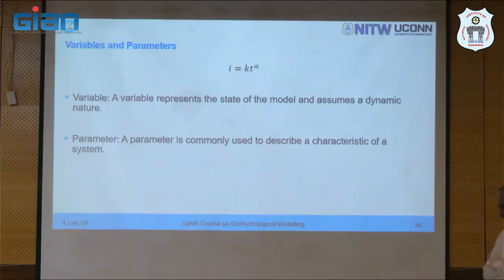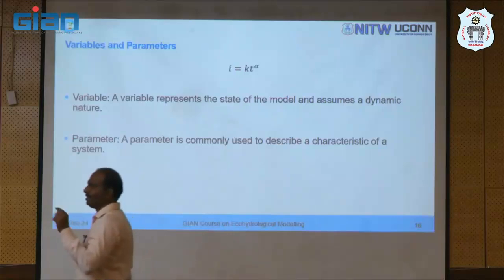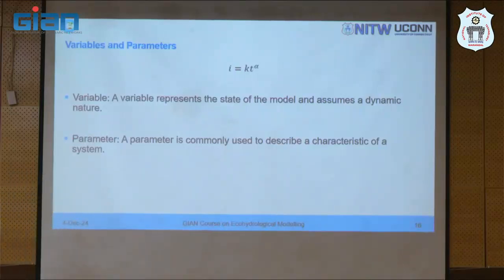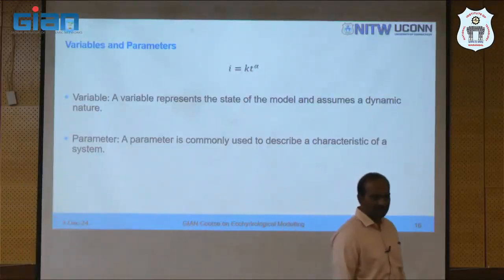It is not exactly a variable. There is an uncertainty, even though they have given a particular value for a particular land use and soil. You see, it's very qualitative information, and that is where we adjust. We adjust the curve number a bit. It's one of the sensitive parameters, right? But it's primarily a parameter because of the uncertainty in how we describe it. It's very qualitative nature, okay?